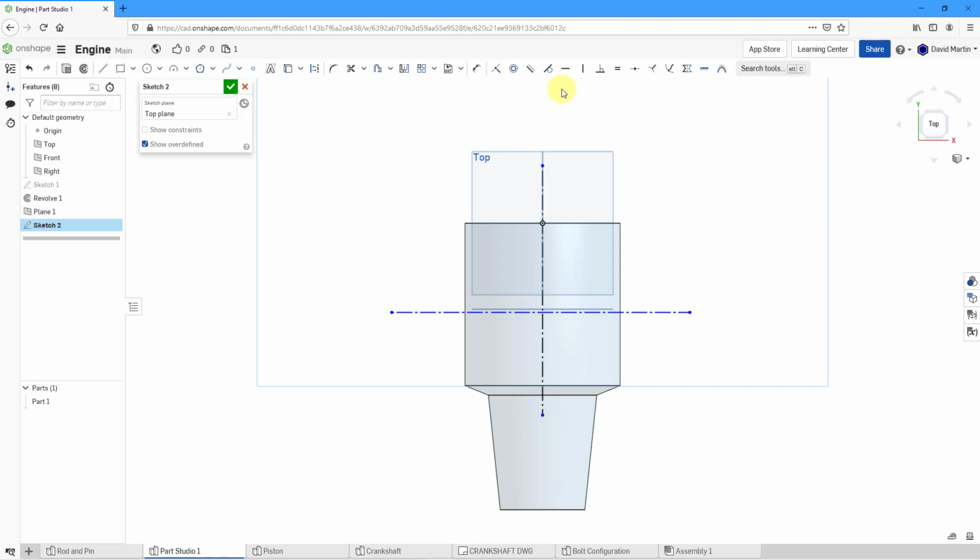And let's put in a constraint for coincident to have it sit right on top of that datum plane that I just created. The sketch itself is just going to be 4 lines. Let's create some lines, and I want it going from here to about over here and then down, and I want it wider down at the bottom than up at the top.